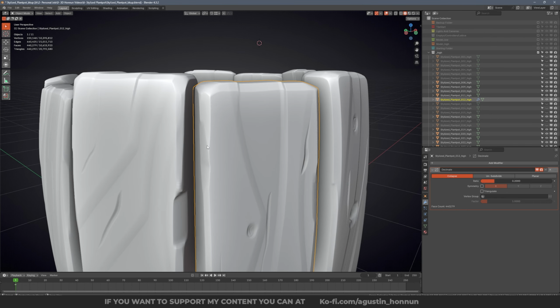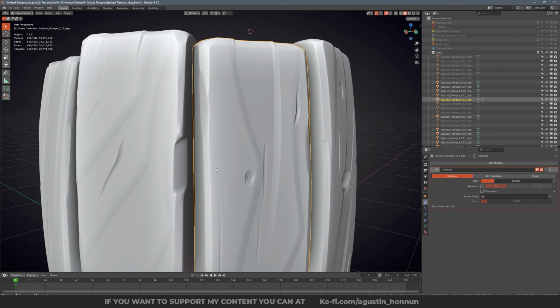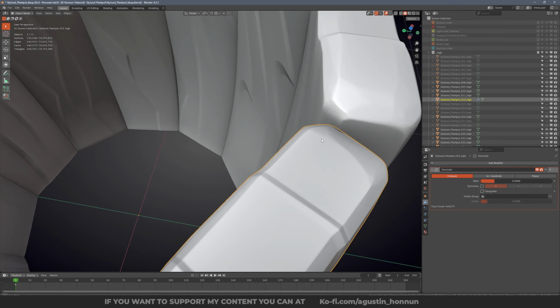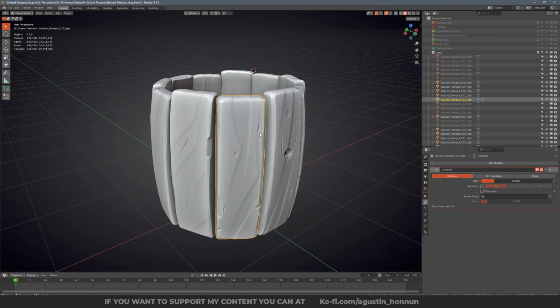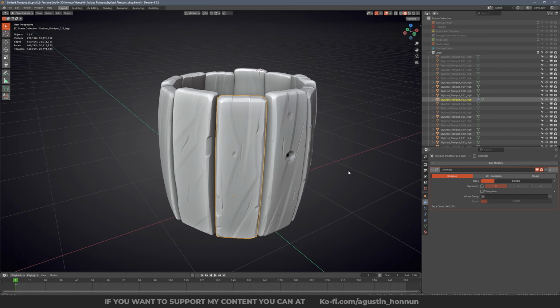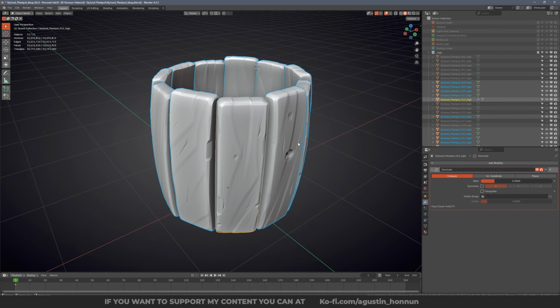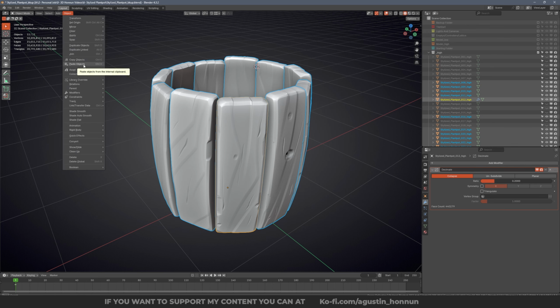We need to make sure we don't have glitches here over the mesh, because that will affect our bake process later. So this amount of decimation works. Select the mesh with the decimate modifier, select everything, then press Ctrl L, Link/Transfer Data, Copy Modifiers, or go to Object, Link/Transfer Data, and Copy Modifiers. This will take some time.